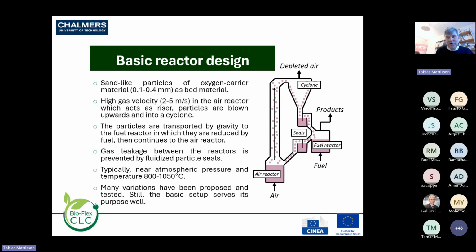Here it's transferring oxygen carrier particles, in the same size range as in normal fluidized beds, perhaps 100 to 400 microns. The gas introduced to the air reactor is both the gas used to oxidize the particles, and also the gas used to transfer the particles via drag forces in the reactor system to the fuel reactor.